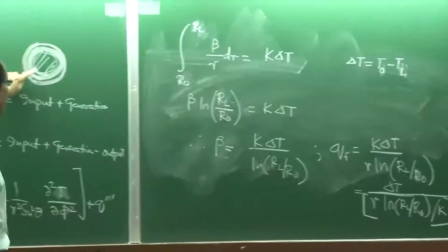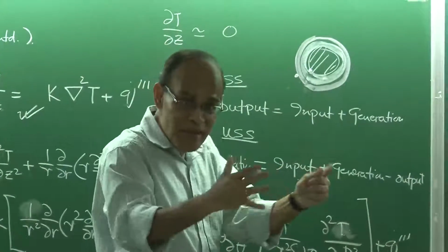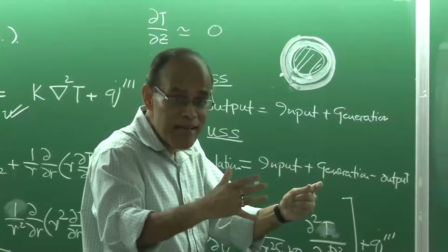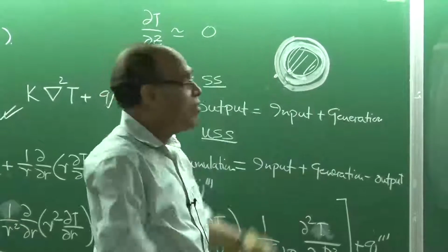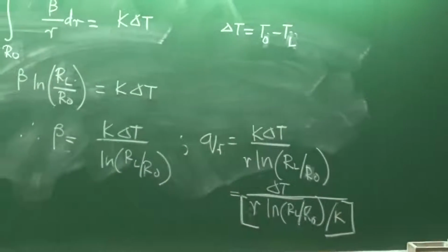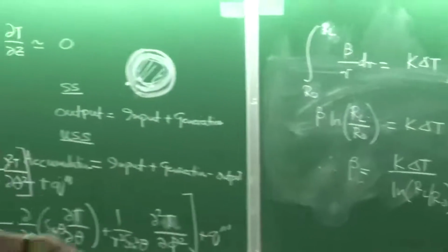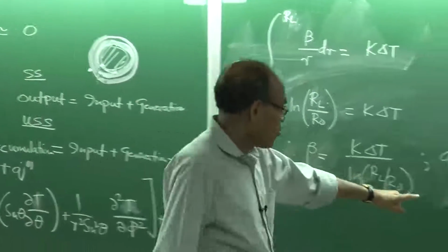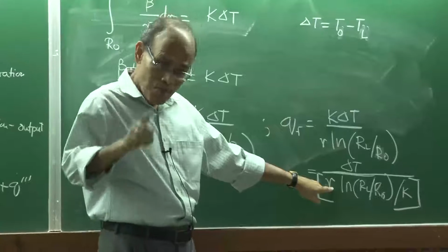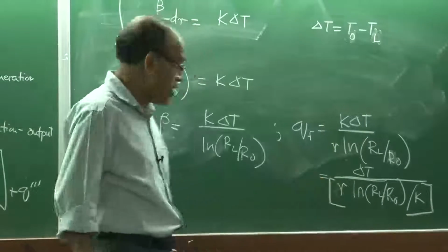So, I should be able to find out the contact thermal resistance here, contact thermal resistance here, add them up, okay, and then delta T divided by the summation of the contact resistance will give me the net rate of heat flow, which is Q, provided I evaluate the thermal resistance by multiplying with R, so that this R does not remain in the expression itself.